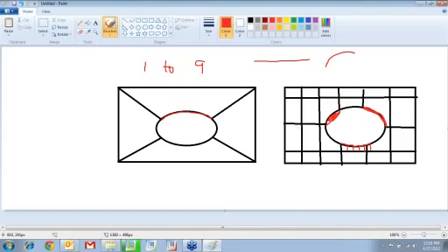Now, another limitation of H-type FEA is that wherever these element edges meet, those points are called nodal points. So if you want an answer over here, you would get an interpolation of all these answers, or you just refine the mesh and create smaller elements. In P-type FEA, you get the same accuracy because there is something called a plotting grid. A plotting grid, when the value is 4, will not only calculate the answer at the nodal points right here, but also at 4 locations along the element edge.